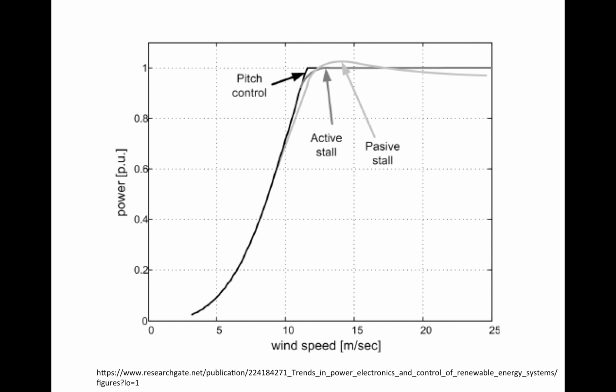If there is a pitch control system, inducing active stall actually takes a shorter amount of time. So the power curve for active stall machines is relatively flat above the rated wind speed. So pitch control can actually bring the power curve closer to the ideal situation.